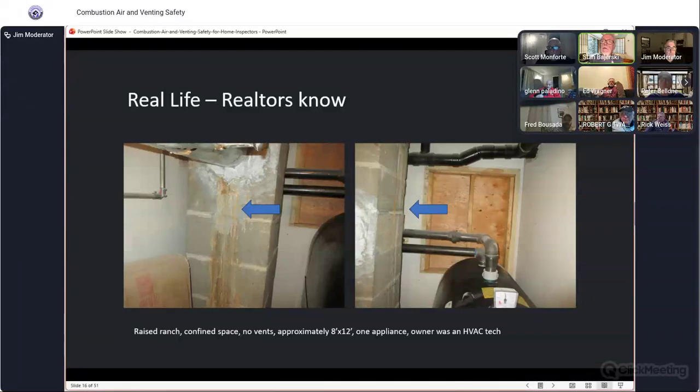The water heater was indirect, so there was one appliance. My eye first caught the water staining on both sides of the chimney that I could see. And up in the left corner, you could see the vent pipe, the smoke pipe, and it was about a 9 to 10 foot run from the boiler, and very little pitch. You can kind of tell in that picture even.